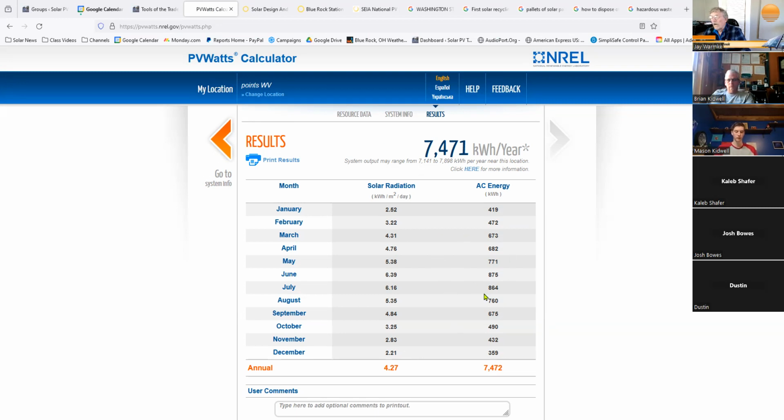Now, in this case, Brian, if this was for your system, we would look at your electric bill, and this is going to generate about 7,500 kilowatt hours per year. The average home in America uses about 900 a month. So you're going to have about 10,800 over the year. So three quarters, a little less, 70% of your annual from that array. So if you wanted it bigger, if you wanted more, well, you'd probably have to find a different location.